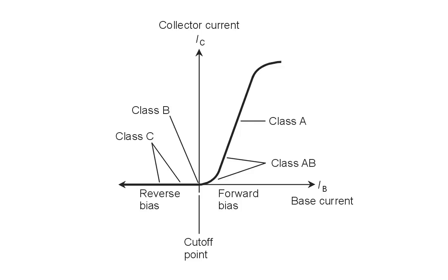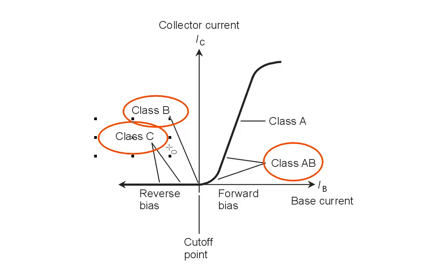These classes of operation, AB, B, and C, will introduce nonlinearity into the signal wave itself, but that does not necessarily disturb the modulation envelope.